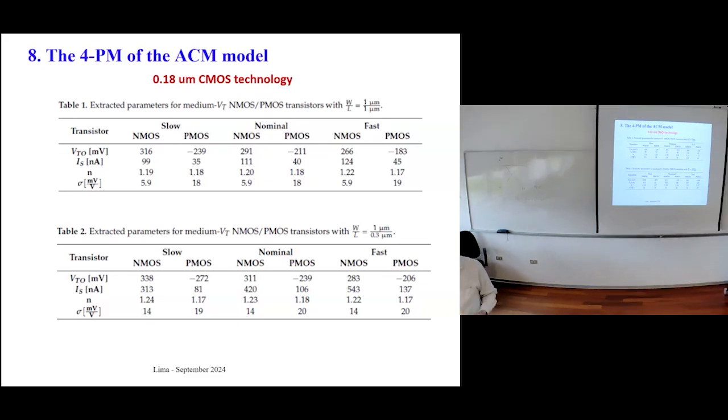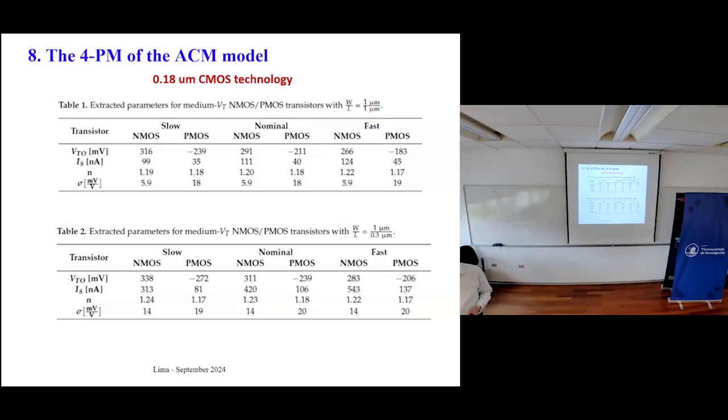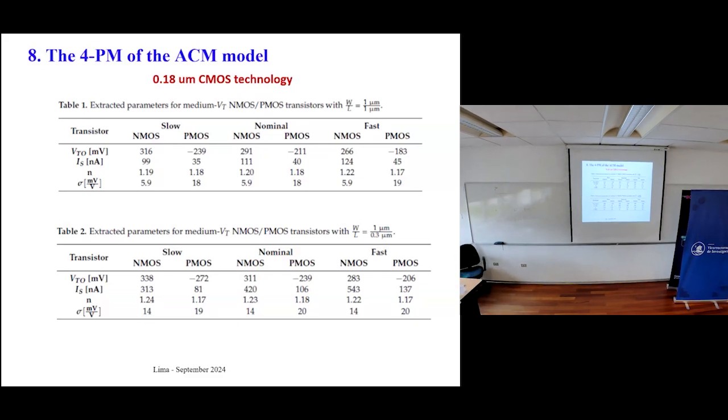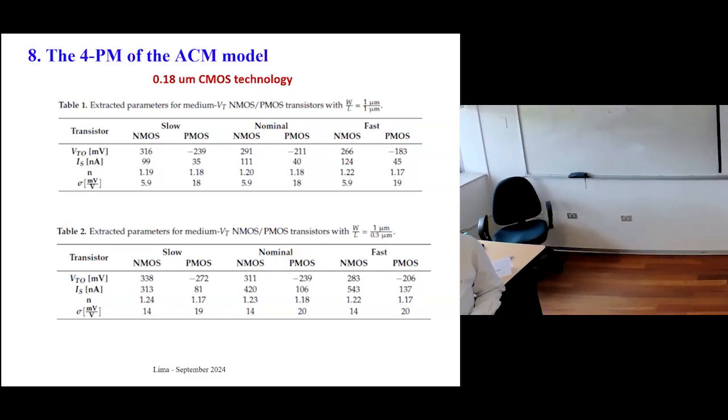It's like taking a resistor from the drawer. The nominal value is 10 kiloohms, but we measure 9.85, 9.7, 10.02, etc. So even if you have the resistor from the same lot, they can change a bit.